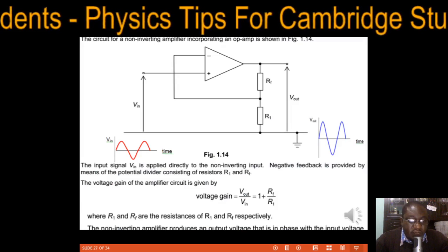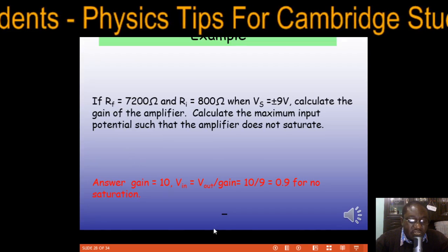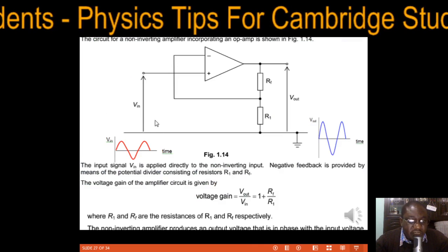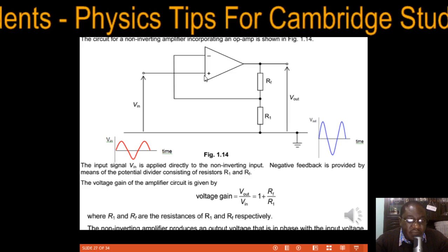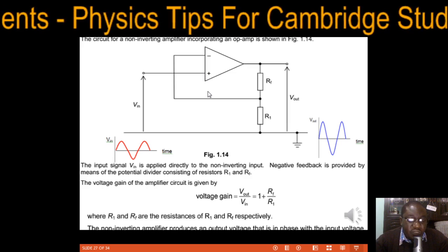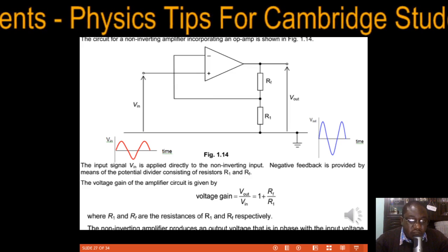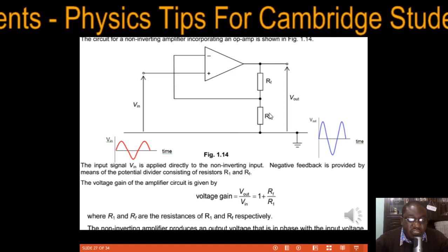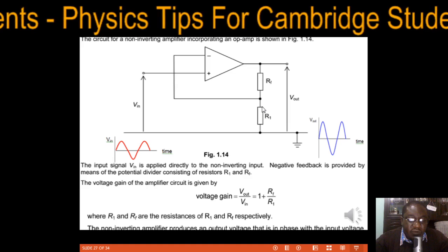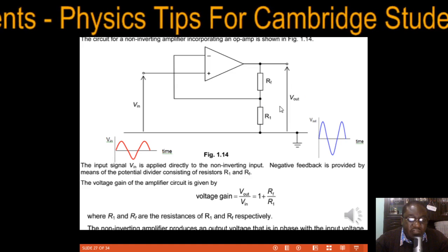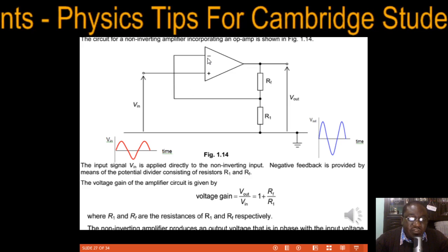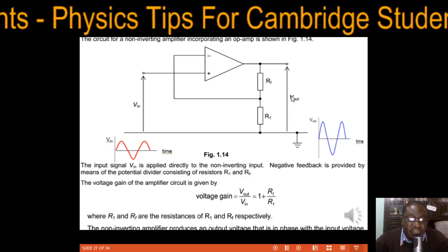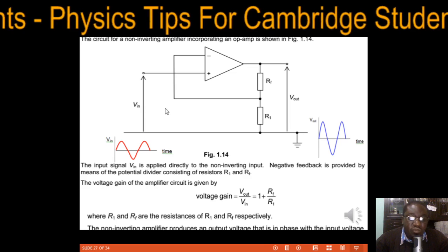Non-inverting amplifier. It's a non-inverting amplifier because Vin is being fed to the non-inverting input. Feedback is always to the inverting terminal, and it is in the form of this potential divider. So we say R1 over R1 plus RF times Vout gives you what is getting in through there. Now, in order for our operational amplifier not to saturate, this value, R1 over R1 plus RF times Vout, should equal Vin to avoid saturation.